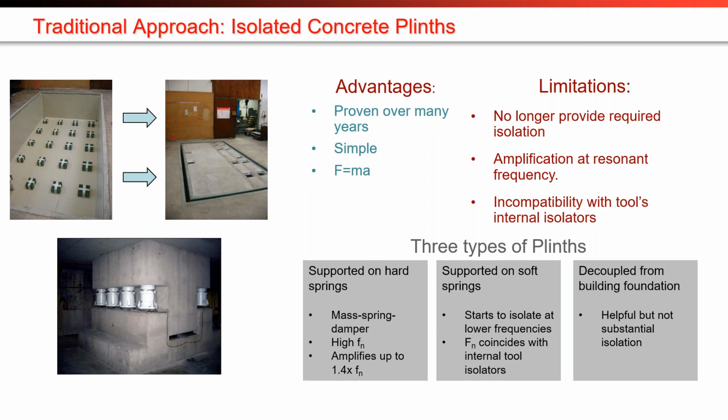So if you've got, say, an electron microscope that has low frequency air isolators in it, and you place it on a plinth that's supported by low frequency air isolators, you can run into compatibility issues between the two sets of isolators being stacked on top of each other. So basically, it's becoming increasingly difficult for the plinths to provide the required isolation, especially at the low frequencies, like below 10 hertz.